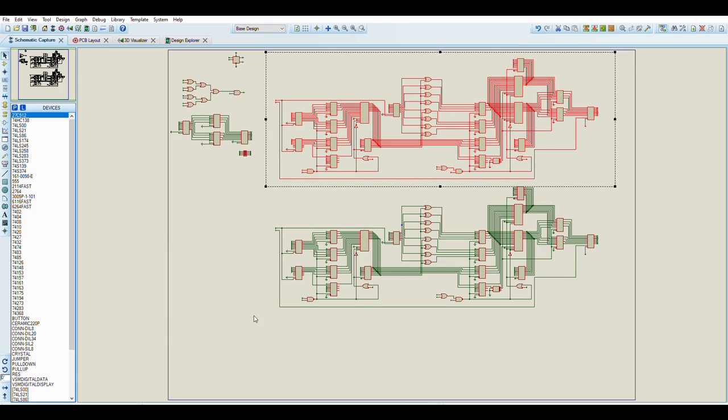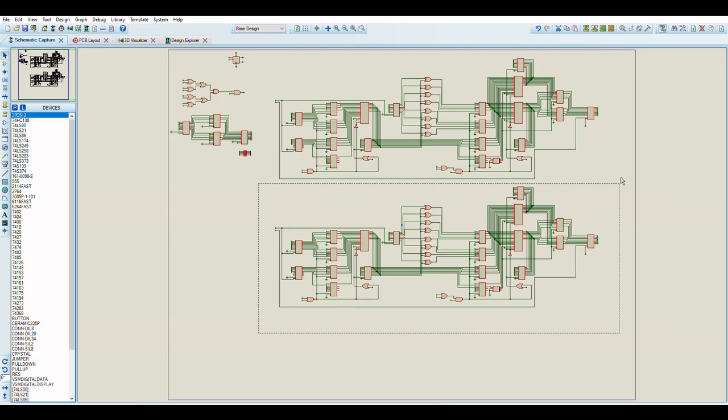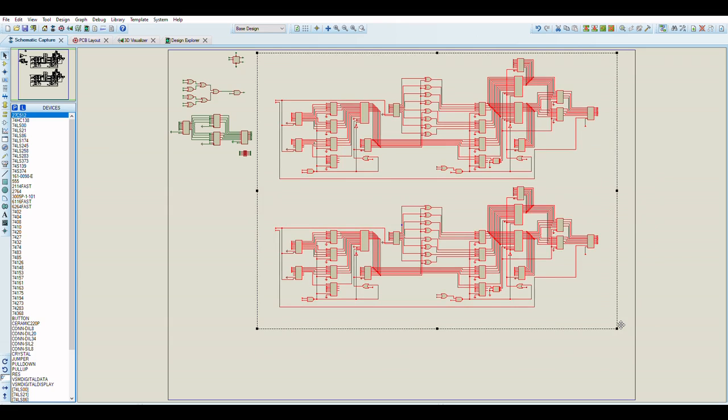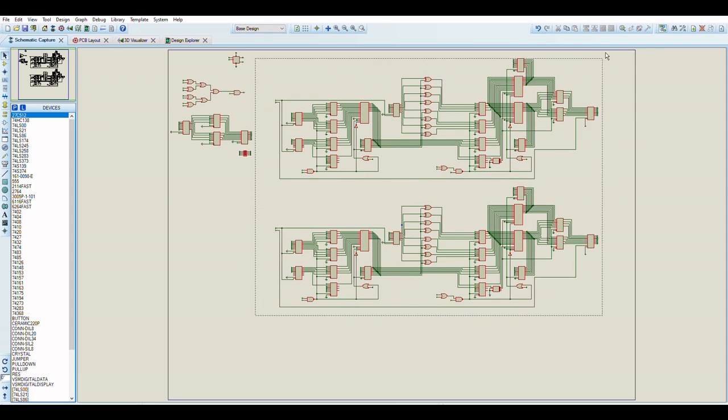I did have the option for going into 4, but I realized that at the particular simulated clock speed for a 60 Hertz NTSC style display, I did not need more than 2 pixel pipelines for the Mode 7 screen. And it's actually relatively easy to understand. Just flows from left to right. Boof, boof, boof. I imagine that when I build this, these rounds are going to get quite hot, but that's okay. They're designed to cope with that.